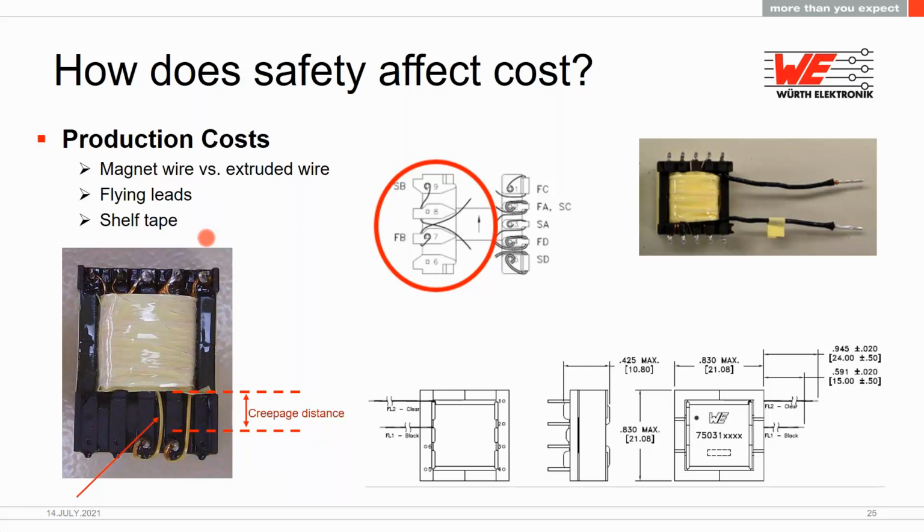There are cases where we have equipment that can apply this tape automatically, but once you get to winding number 2, 3, and 4, you're now applying this shelf tape over the top of the previous lead wires. This can create inconsistent areas for that shelf tape to lie and can make consistent automation nearly impossible.